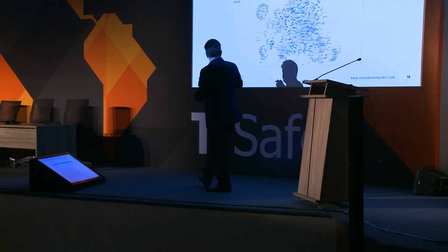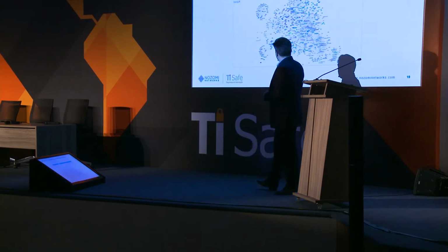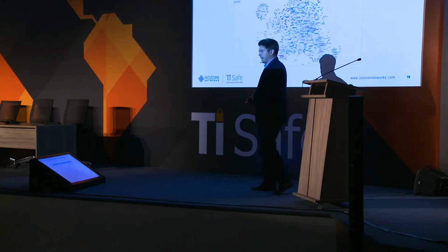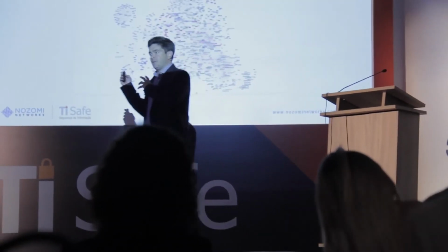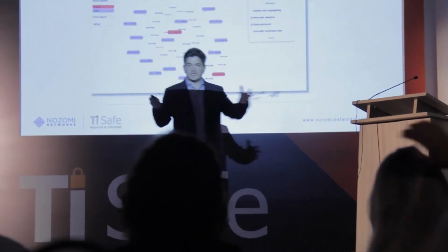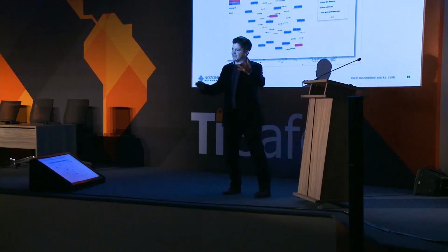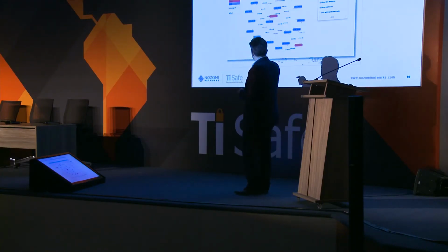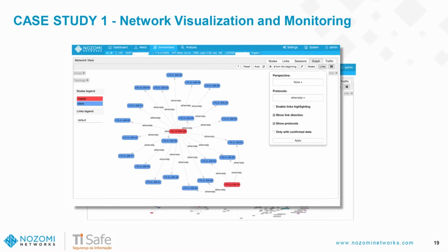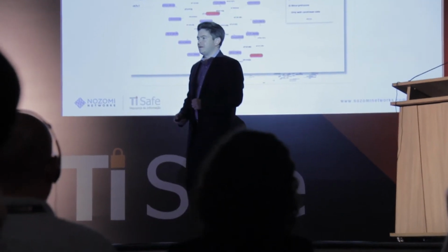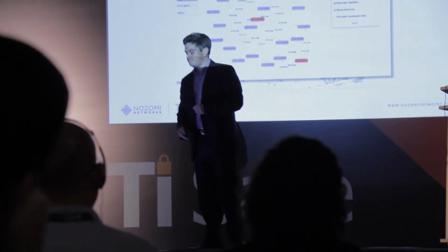We also start mapping the network hubs, network segments. And somebody, Chris in this case, was able to now drill down, for example, into this particular section of the network and examine it better, right? We now understand that this is EtherNet/IP, this is Modbus over here, this is the SCADA master, these are the PLCs connected to that SCADA master, so you start gaining visibility into that network.